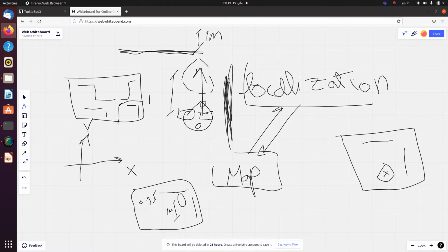So whenever I keep going, my localization sensors could help me determine where the new obstacles are. So if I know that, for example, I moved right here, my new local map says that I moved a distance of 0.5 meters to the left, and I rotated with a theta that is equal to, for example, 120 degrees.